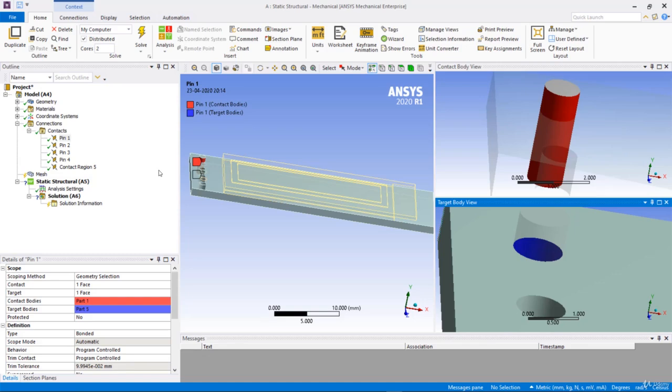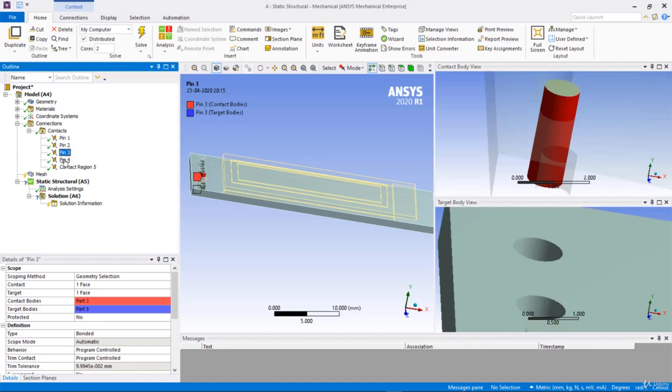If you come closer and observe different contacts, every contact type is only bonded. So whenever you take in an assembly, whatever automatic contacts are created, they all act as a bonded contact only. So this is the thing you need to change manually.